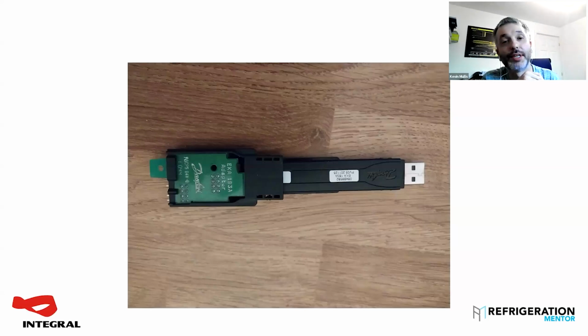And you can either use that to extract all the settings out of a controller you know to be good, or you can use it to drop settings into a controller that you want to set up. It takes like 30 seconds to go through its cycle, and you've got a fully programmed controller. Even if you don't know what settings should be in that case, if you haven't got that information to hand, you can suck all that information out of the case next door. And if that case next door is working, you're pretty sure that one's going to work on those settings and it will get you going.